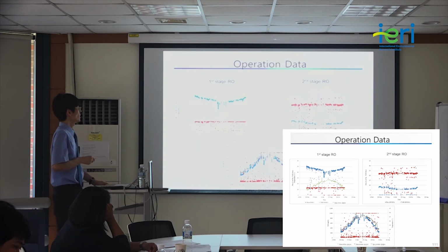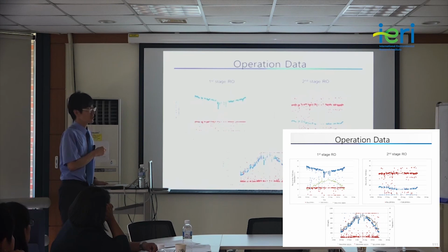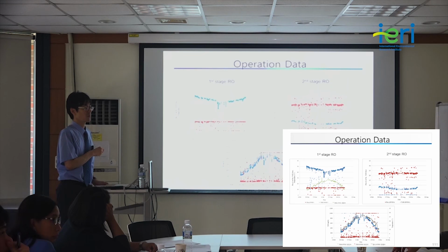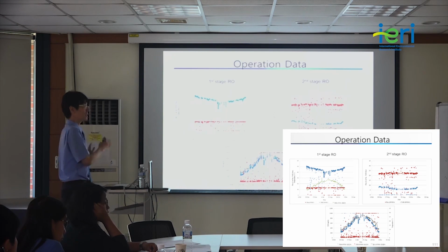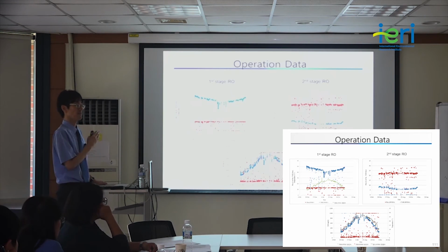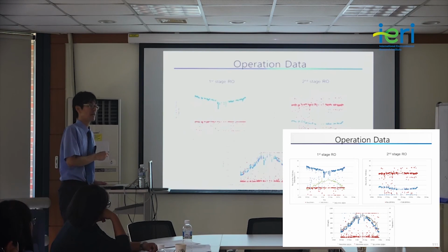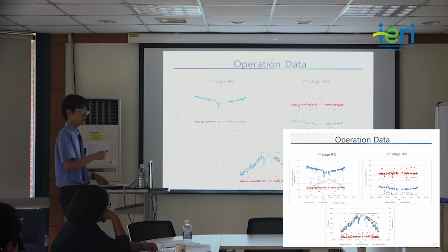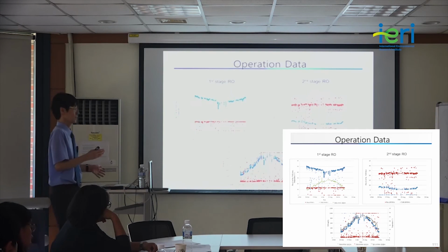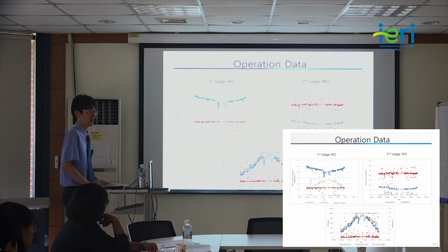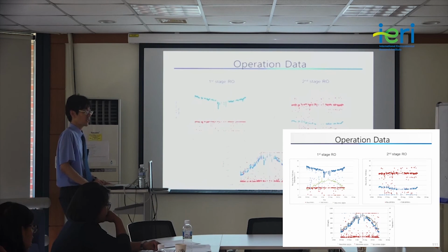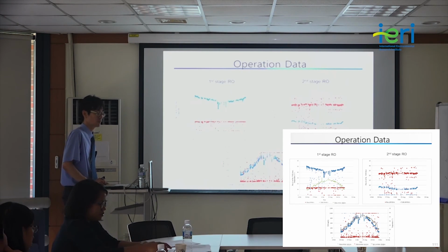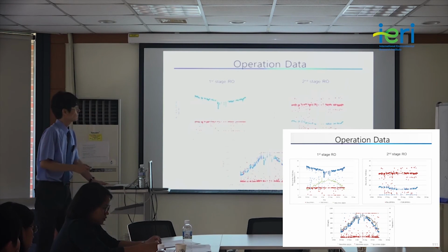So in fact, when we operate the desalination plant, we don't want to adjust the water production rate. So if this plant capacity is 250 cubic meters per day, we always have to maintain the same flow rate. In other words, we always have to maintain the same flux because the membrane area is fixed. So by maintaining the same flux, we can always get the same water production.